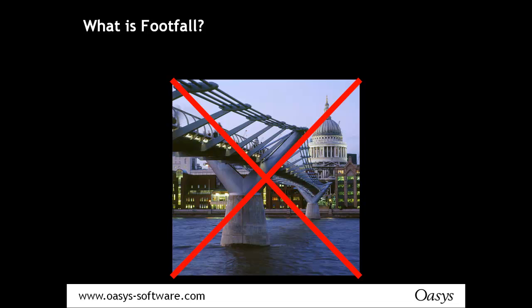If you get horizontal vibration, you have to walk in step with it, which means you then get a feedback between the people walking and the bridge, and everything gets worse and worse. Vertical vibration is different in that you do not have to walk in step with it, and therefore you do not get the phase locking or the feedback loops that you can get with horizontal vibration.